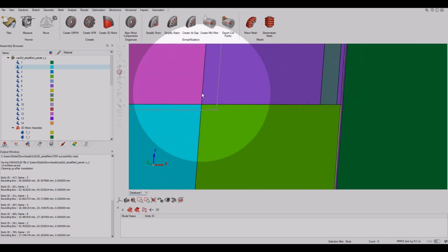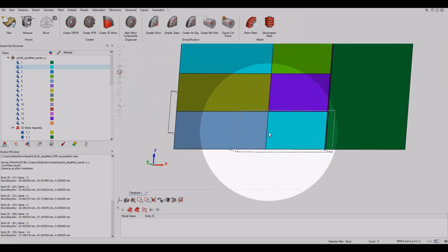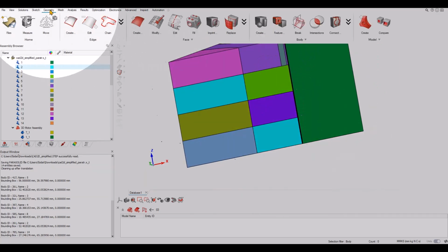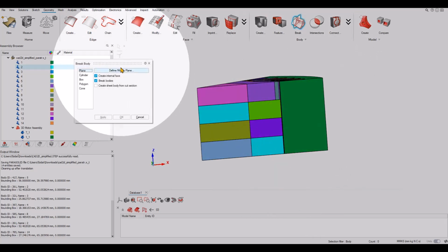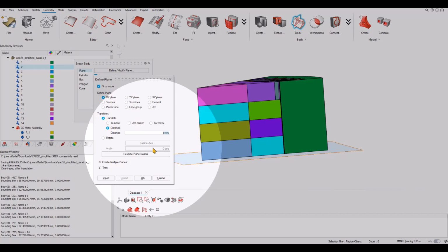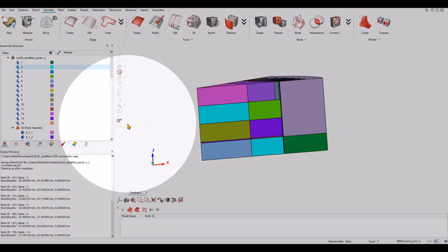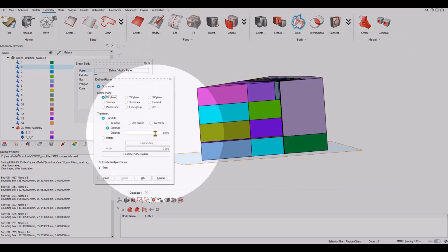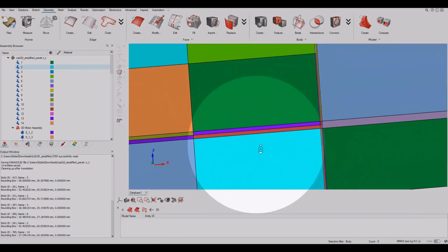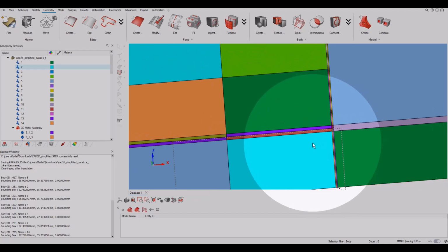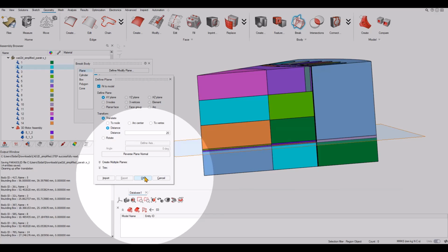What I want to do today is to add some layers in the junction in order to mesh this area well, because there are some eddy currents inside this area which return in this area, in addition to the leakage magnetic flux between layers. So to do that, I am going to make some cuts corresponding to the layers, and also additional cuts in the top and the bottom of each layer border.